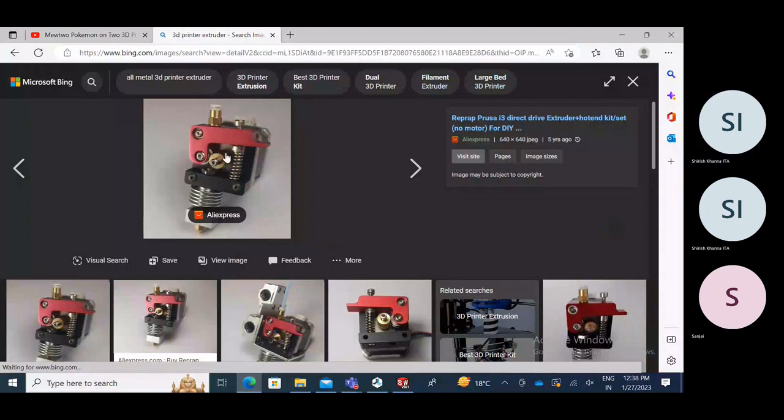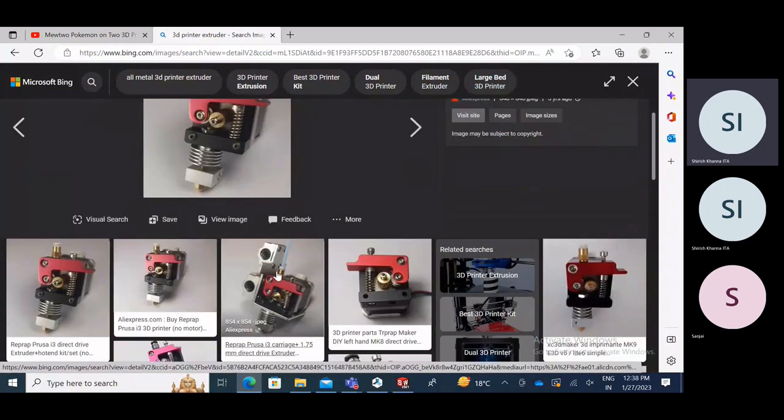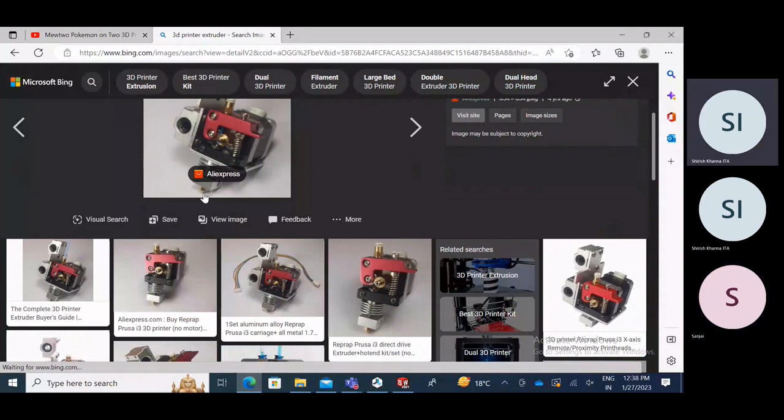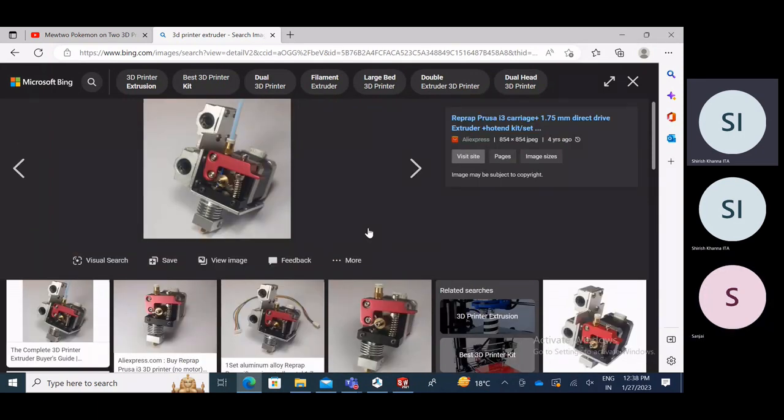Okay, this is the extruder of the printer. Now you can see the filament also there. See, the filament just passes through this side, it is melted inside, and then it passes through the nozzle. This complete set is known as the extruder. Suppose you are printing and in between cooling down happens, then the material will be converted into solid again, between from this to this.